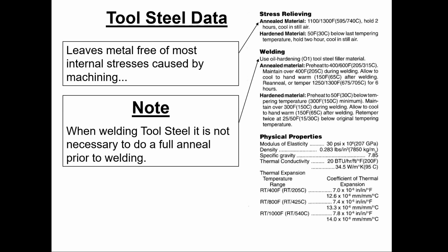I cool everything on a piece of wood that comes out of something like that because I don't want the temperature of the bench to affect one side more than the other, and it will. So here's a good example of what a good welding procedure looks like, right? These last two pages, because they define all the things I've been talking about: understanding your procedure. Now, you may have a special procedure that requires doing something a little bit differently, and that's fine. And you can always contact me if you get into some really tough materials with D2s and you're getting cracking and all that. But we can figure everything out.